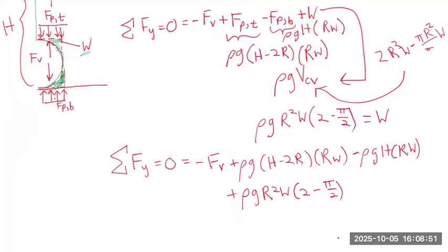And now we can solve for FV, which is the vertical force the cylinder exerts on the control volume. This vertical force will be equal in magnitude to the vertical force on the cylindrical portion of the wall, which is equal to the total vertical force, since there's no vertical force on the initial vertical portion of the wall, since the pressure force will be parallel to that wall.